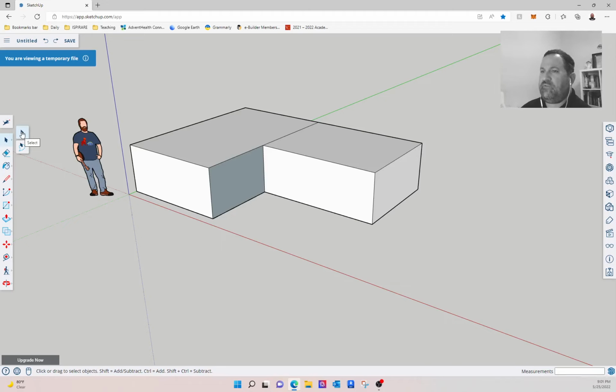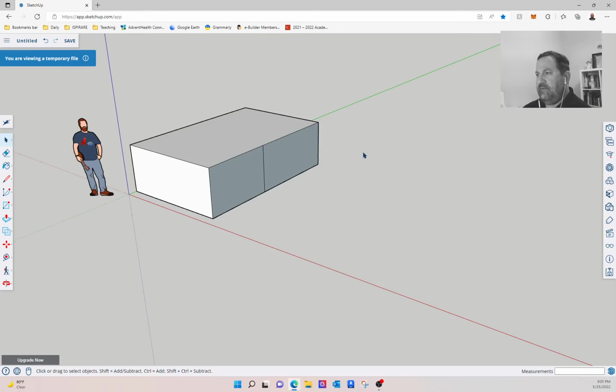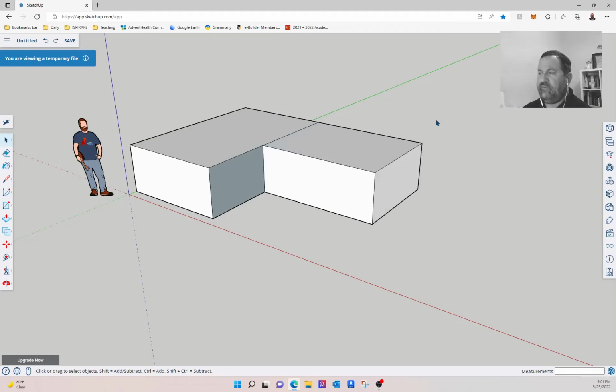Here's what I mean. So first I'm going to select the extrusion we made last time and delete that. And then I'm also going to delete, by the way, let me back up. Control Z undoes the last work. If you left click, hold and draw left with your mouse, that's called a crossing window. And everything the crossing window touches will become selected.